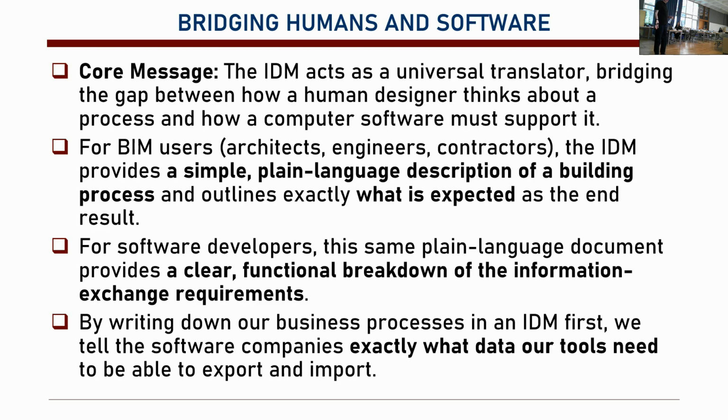And we use different software. But of course, with BIM, we try to stick to a simple exchange protocol, a simple creation process of the whole model, and exchange something that is interoperable, something that we can exchange easily between each other. So that's the idea. For software developers, it also provides a clear functional breakdown of information exchange requirements, like: you need to deliver an IFC model about spaces, an IFC model about structure, etc.